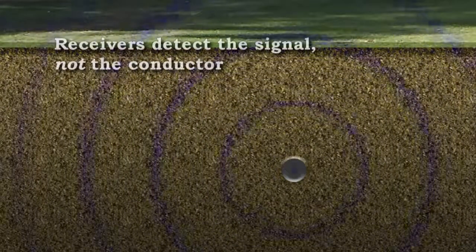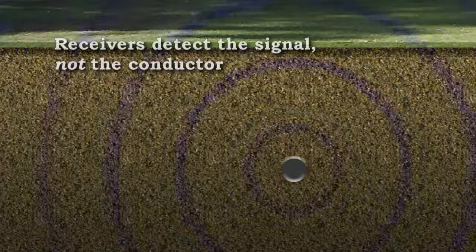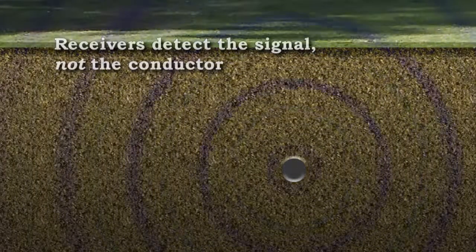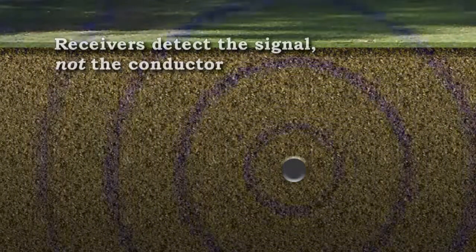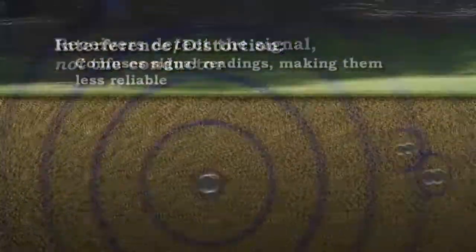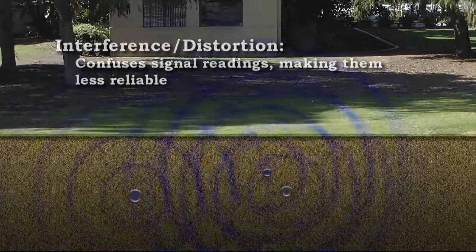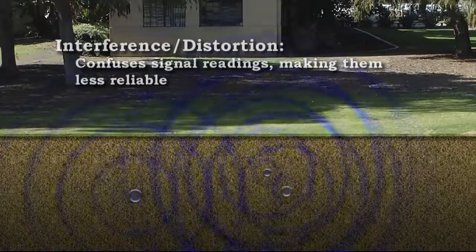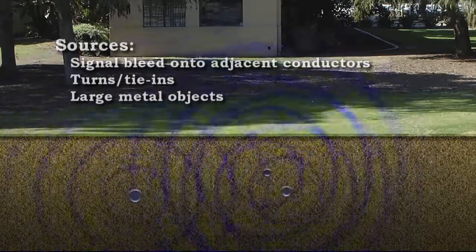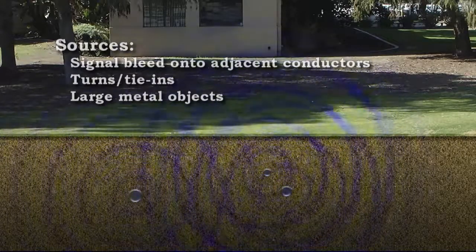When designating a utility's position, it's important to understand that the receiver is actually tracing this signal and not the utility itself. You are assuming that this signal accurately indicates the utility's location below ground. In favorable conditions, this is generally true. Quite often, however, conditions exist that interfere with or distort the signal, which can make the signal readings less reliable. Some common sources of distortion are signal bleed onto adjacent conductors, turns, tie-ins, and large metal objects such as manhole covers, vehicles, and fences.